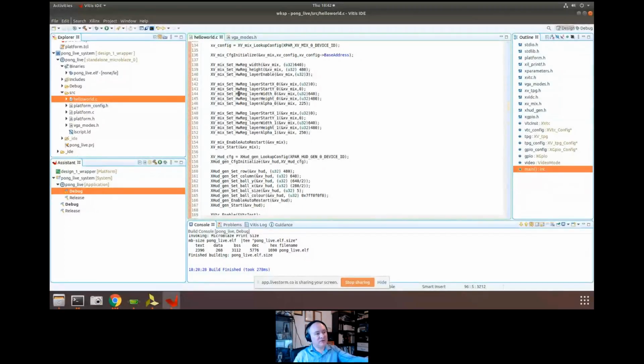With the first one, we're setting up the hardware register layers to enable layer 1. Although it says 3, it's actually the binary bits that you're enabling. We're telling the video mixer that we want to mix a 640 by 480 video, and we're enabling layers 0 and 1. Then in the next rows, lines 142 to 146, we're telling it where the video starts in that next layer. So it starts at 0, 0 and it ends at 640. This is not so useful for our application, but if you wanted to do picture in picture or something like that, or tile images together, we could do that.